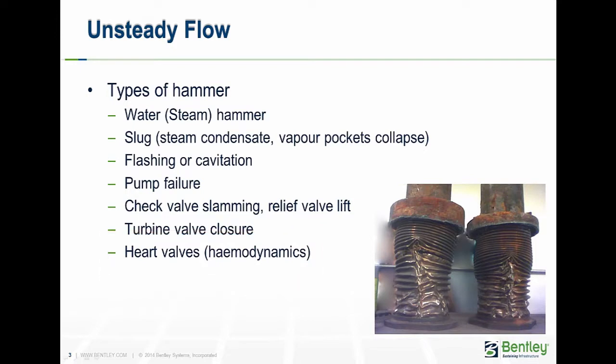To illustrate the potential magnitude of such forces, let's consider a perfectly rigid pipe with entirely incompressible fluid and an instantaneous valve closure. According to Newton's second law, bringing the contents of the pipe to rest instantaneously would result in an infinite force. Thankfully, fluids are not completely incompressible, especially gases, nor pipes rigid or valve closures instantaneous.